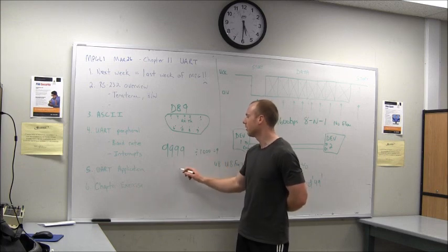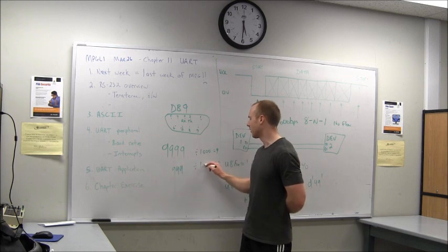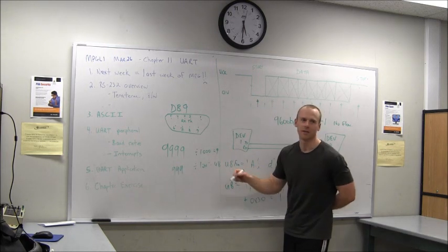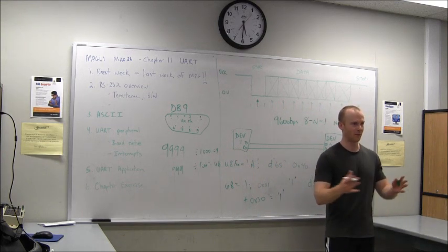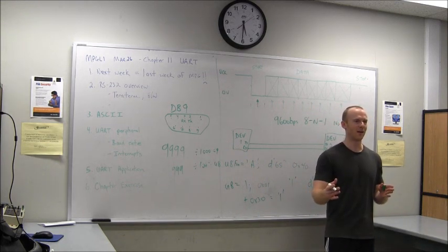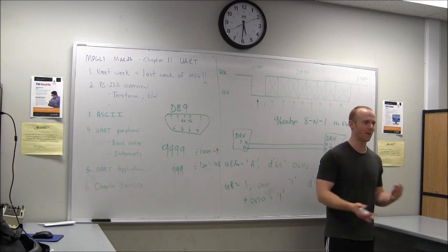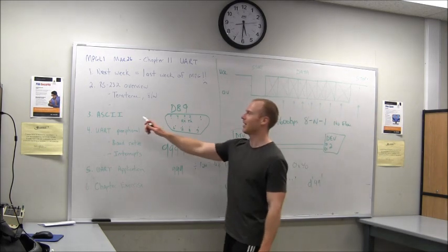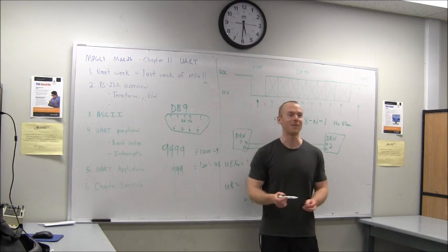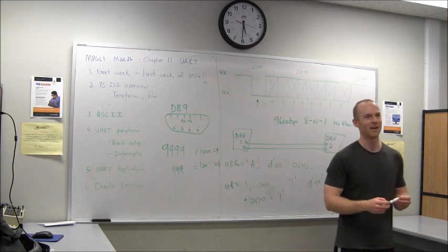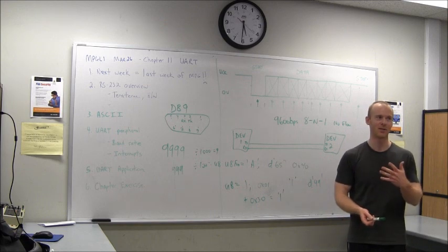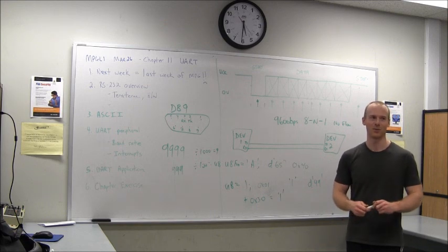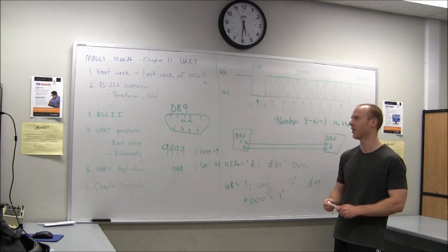And you take the remainder and divide. So the remainder is 999, and you divide that by 100 and you get 9. Each digit that you get, you have to convert that to ASCII and prepare your number in an array, like a string essentially, and then print that out. So this becomes a total pain in the butt when you need to interact with a human user that only looks at ASCII numbers, because we don't do hex very well, or we don't do binary very well.